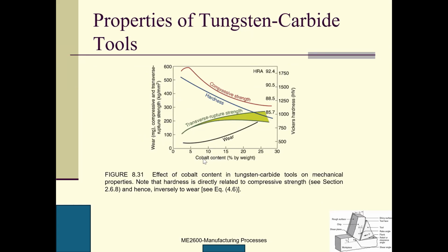So you can see as the cobalt content increases, the wear is increasing. The transverse rupture strength is increasing also, but hardness and compressive strength, both of them, are dropping as the cobalt content increases.